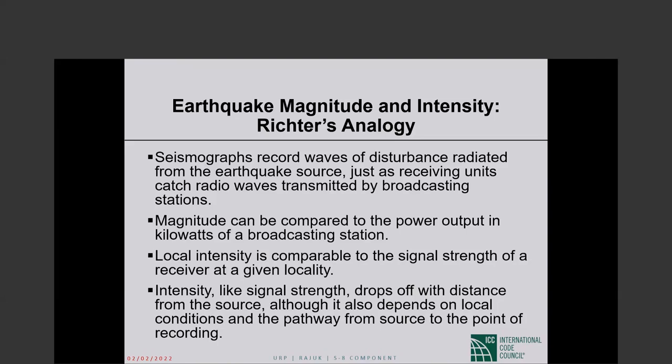Okay. Intensity, on the other hand, is what is felt in that earthquake at your particular site. What is felt at your particular site will depend upon definitely the magnitude of the earthquake and other attributes of the earthquake. Was it a strike slip fault, like lateral movement of the fault? How long was the fault movement?